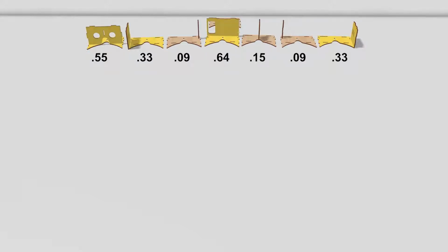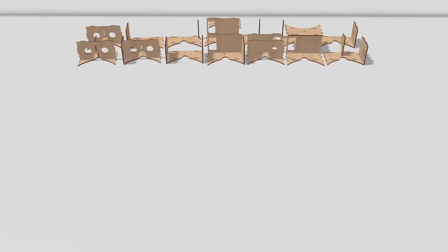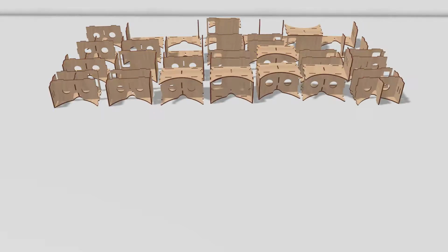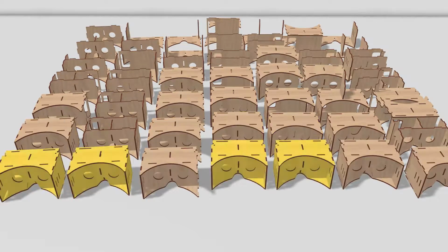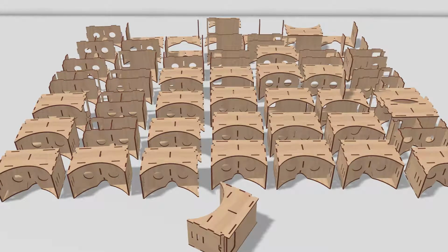Testing showed that a beam width of 4 was sufficient to reach a high success rate. This means that it takes the 4 best scoring candidates and generates new children from these. autoAssembler recursively performs this procedure until all plates are assembled. The key to the success of this algorithm is the heuristics function that calculates the scores based on the weighted sum of 6 heuristics and 2 procedural steps to narrow down the search space at each stage.